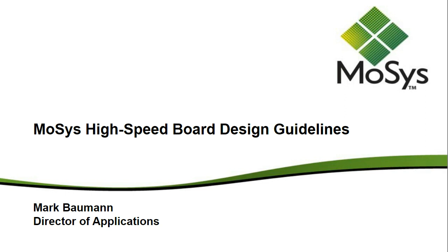So we took that 1T SRAM, very efficient memory block, and we bought two SerDes companies, one for high performance, one for low power, and created a family of ICs called a bandwidth engine, which is a very high speed and efficient way to get data in and out of your host processor. So we took away that bottleneck in getting to off-chip memory by interfacing to the host, whether it be an ASIC or an FPGA or an NPU via SerDes. So very efficient protocol. We created it called Gigachip Interface, GCI. It's an open standard, and it's just a simple way to get memory in and out for high-speed processing. As data rates go up to 100 gig, 200 gig, 400 gig, it becomes a bigger and bigger bottleneck, and we solve that with this family of products.